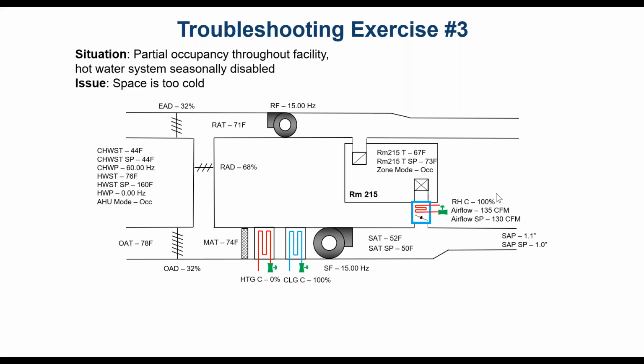All right, step 4, is the manipulated variable as expected? There are kind of two different manipulated variables here. Is the airflow really tracking on set point? Yeah, more or less. We're getting 5 CFM more than we wanted, but for all intents and purposes, we're basically tracking on set point. 5 CFM is not going to be a big difference here. How about, are we raising the temperature of the air going into the space? Because we should be with a 100% open reheat coil.